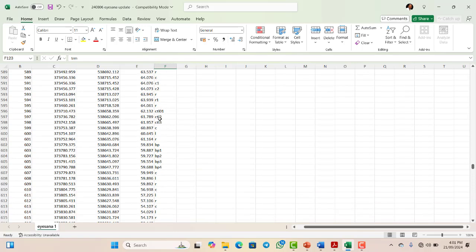Okay, this is something I wanted to really explain. Now, CTL2, CTL3, and CTL01 simply mean control. They are temporary benchmarks. This is a point where, when you want to set out the road, you have to locate this control. You have to know the coordinates of each of the controls. This is where the setting out of your road commences.